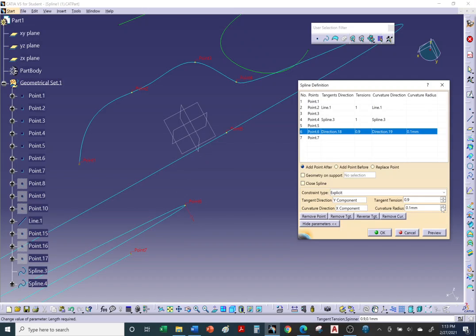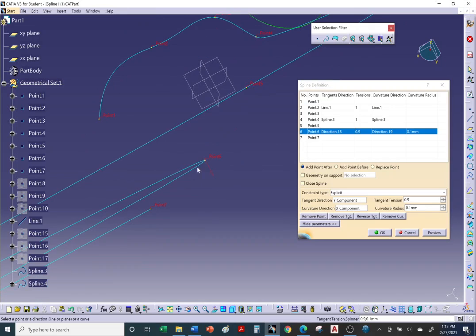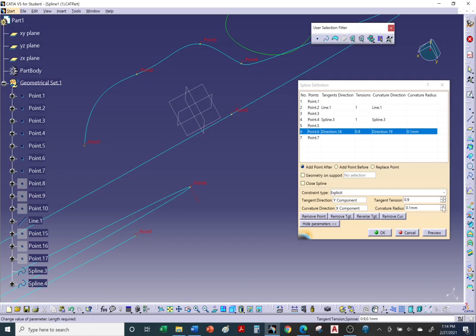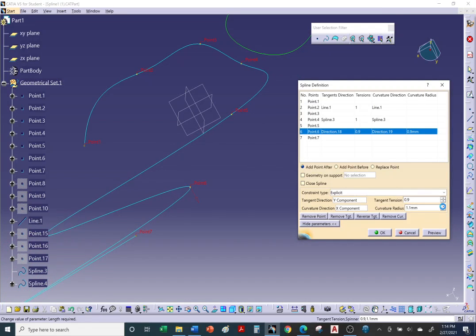And now I can add a radius. See how tight that radius is? We don't want a thick cable to make this tight turn, right? 0.1 millimeter radius, that's way too tight. So I'm going to increase it and watch what happens. Okay, so it's trying to adjust itself to a minimum curvature radius, right? So if the minimum radius was 10, I'll just use 10 or something higher, right? And that's so you don't damage the high voltage cables. You don't want to damage those metal cables inside.